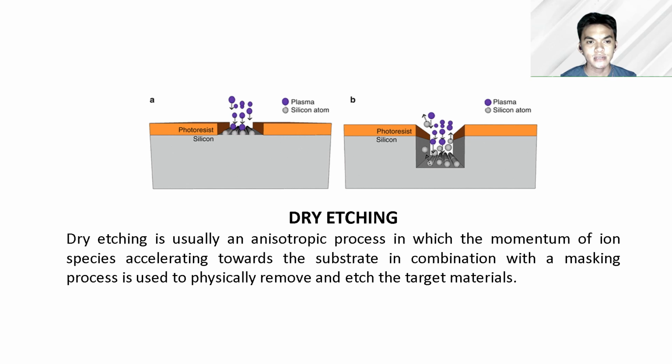The third method is reactive ion etching, or RIE. It combines the first two methods. That is, while using plasma for ionized physical etching, chemical etching is performed with free radicals generated after plasma activation. In addition to the etching speed exceeding the first two methods, RIE can use the characteristics of ion anisotropy to achieve high definition pattern etching.